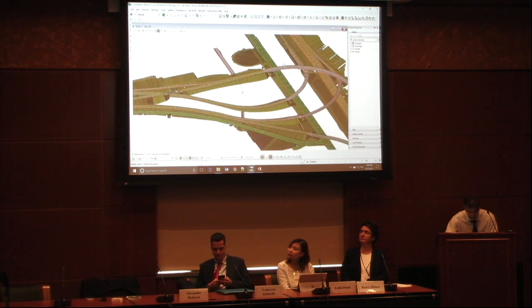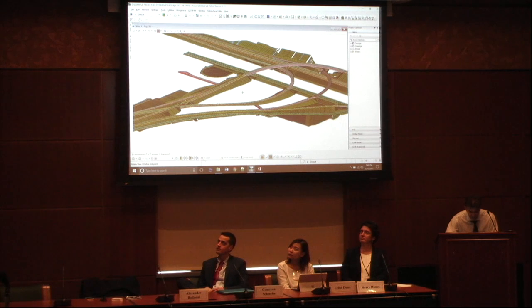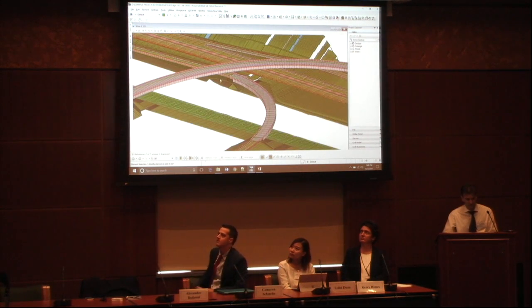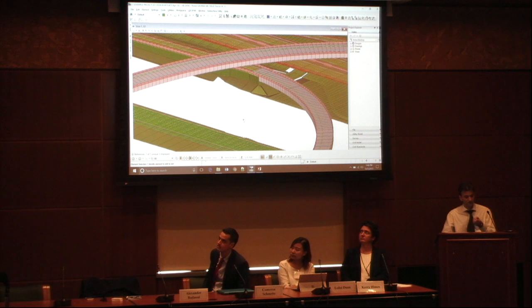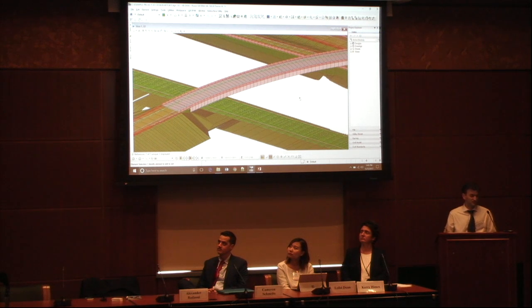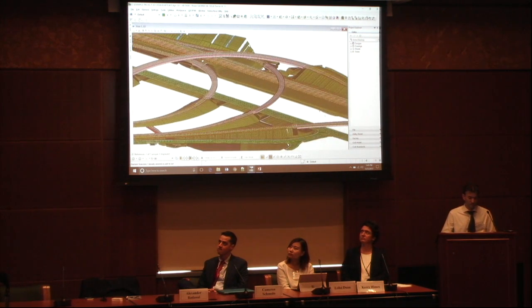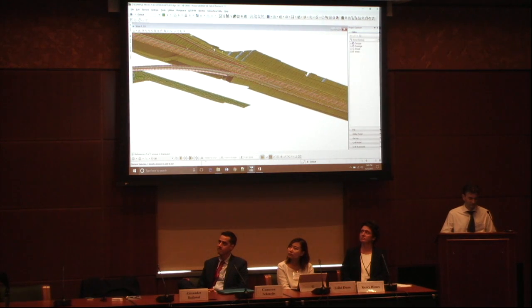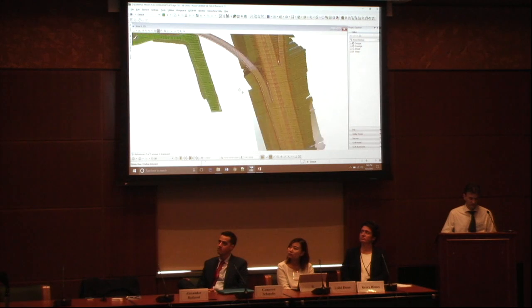So this here is the 3,000 corridor beast. Multi-level interchanges, retaining walls, all the superelevation is done, all the lane pavements are done, the barriers are done, all the end conditions are correct because it's based on what the engineers wanted. The parts that aren't in there are utilities, because another program superimposes those, and the substructure of a bridge, because another program superimposes that too. But all the civil elements are there. It's a concept phase, so we didn't bother modeling the rest of the guardrail, but we got most of this job. And you can zoom in and have a look.